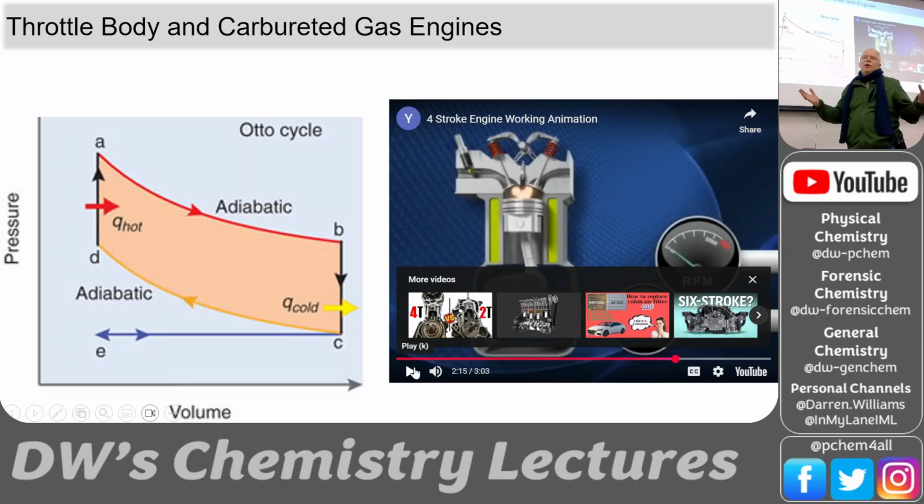And it's the vapor that burns. So you don't have a good explosion, so you don't have a good power stroke, so it doesn't go all the way around to compress the gas. When it gets to the compression step, if it doesn't have enough energy, it'll stop. And so you pull it and it's going around a few times, but it doesn't have enough power stroke to get it through the compression step.